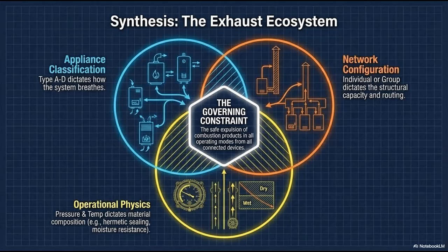Precisely. The condensation forms directly inside the air intake as the steam is drawn backward by the draft, or the ice builds up externally like a glacier over the fan. Oh, man. Within hours, the intake chokes itself off completely. The boiler's internal airflow sensors detect a pressure failure, and the entire system abruptly shuts down. Leaving you without heat on the coldest, most brutal night of the year.